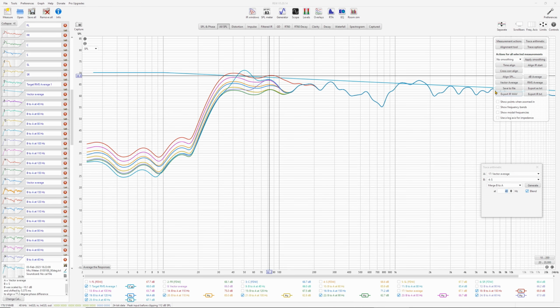Very flat, perfect frequency response doesn't always mean it's the best sound possible. I have a lot of experience with stereo speakers with much accurate filters, and in fact, the less you boost the dips, the better it sounds. So I might try that on Audyssey at some point. Another option in my mind is calibrating with moving microphone measurement technique, which is known to give very good results and is suitable to Audyssey as it doesn't require or contain phase response information.